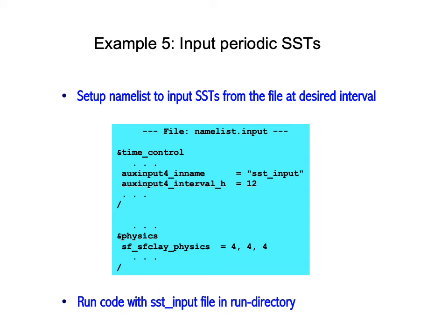We didn't go into what the new surface scheme actually did. We simply assumed that there was a shell and that routine existed. But the part where the data gets into the WRF model was not discussed because that is handled automatically via the WRF code because of the way that we set up the registry with the auxiliary input stream being number 4.